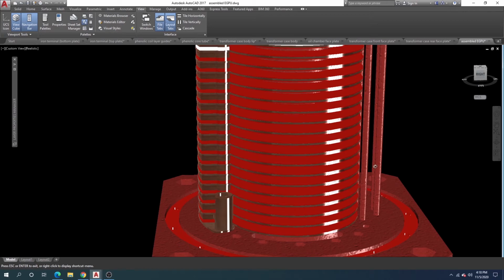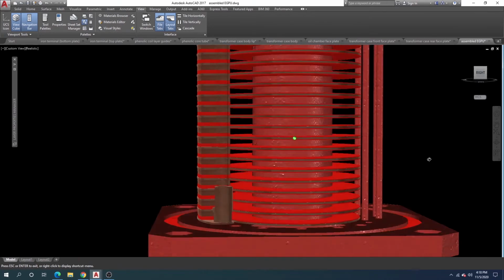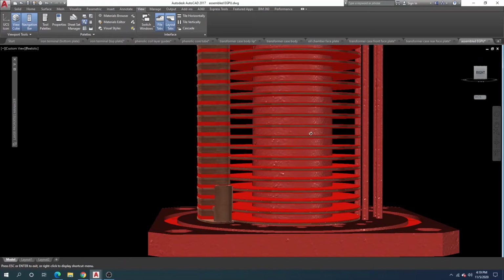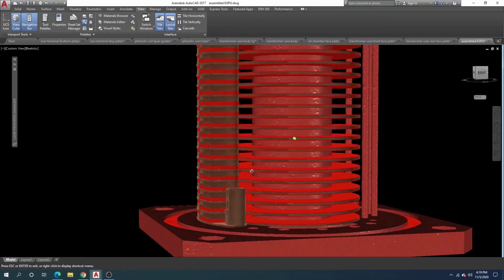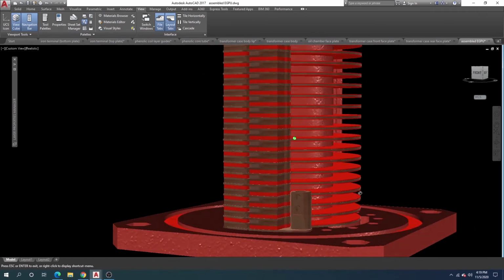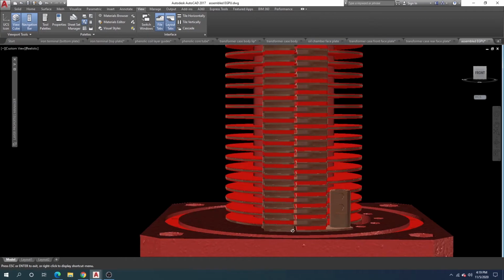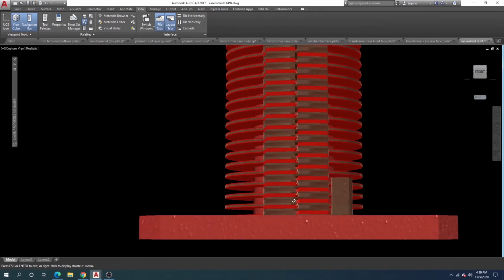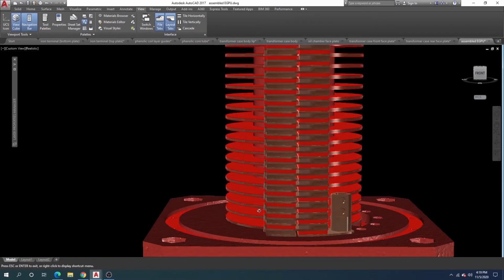Okay, I have right here, these coil layer guides. I have, as you can see, the core tube right here. And so the way that you assemble this thing is simple. You just stack all the layers. And so these coil layer guides maintain perfect location alignment, so the stacks will align in this configuration, which will form this coil.